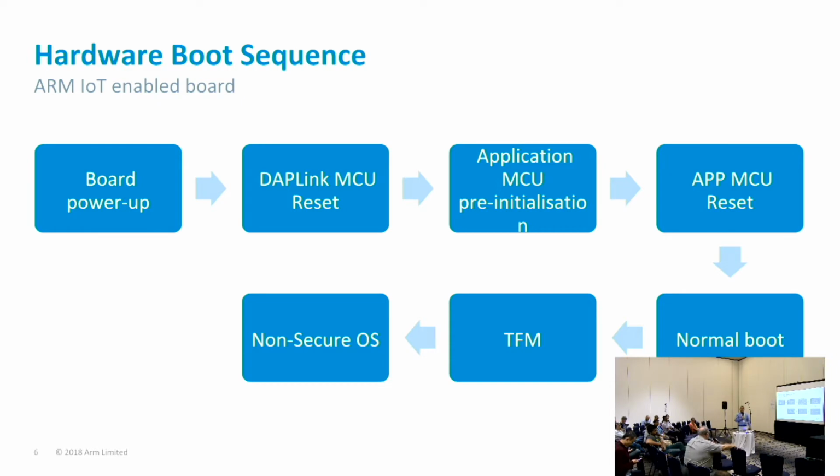Yeah, in our case, we don't have a DAP link, and on our development boards, if you put them in secure mode, you still have the same thing as production. There's no distinction. You have no control once you put it into secure boot. You can't undo that, and we don't have a DAP link or anything like that. So maybe in that case you do a QEMU simulation or something. I'm not quite sure what you do for the testing of this.